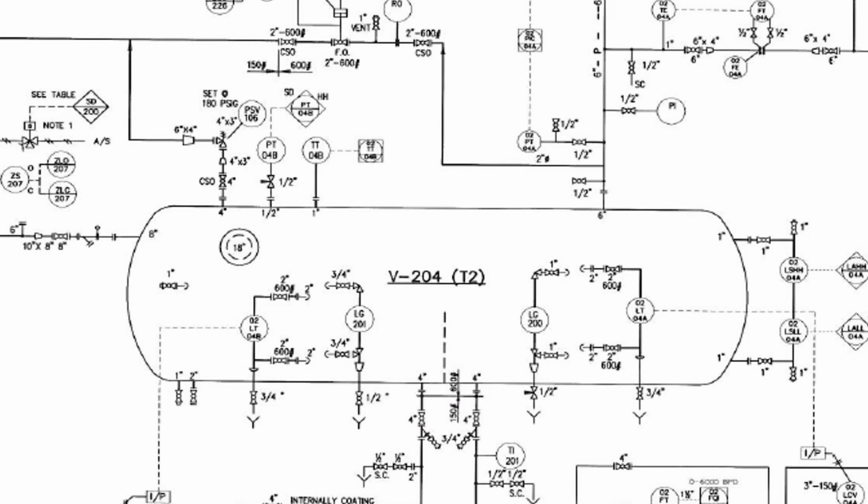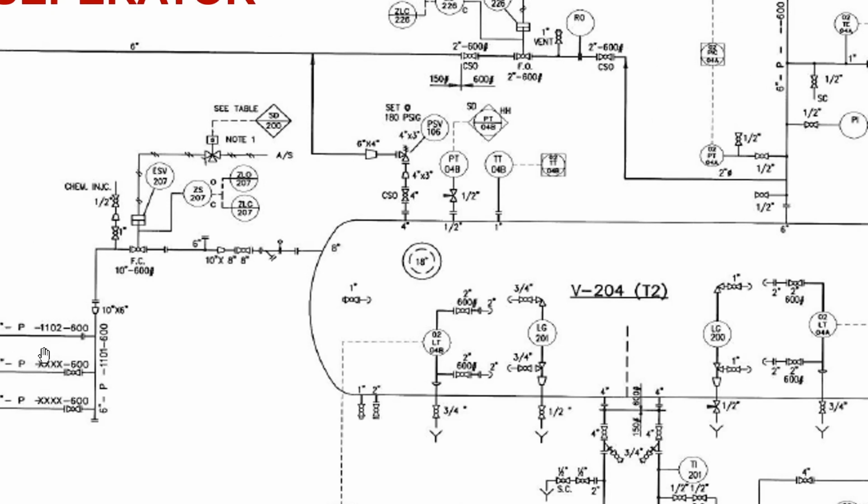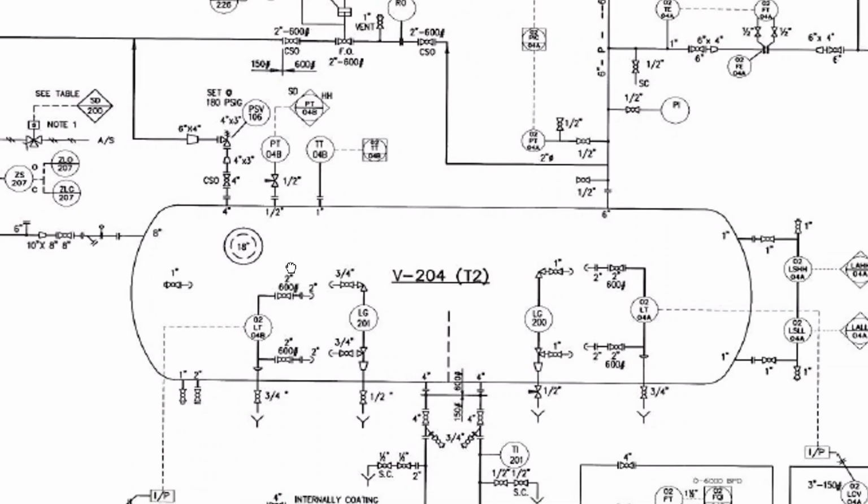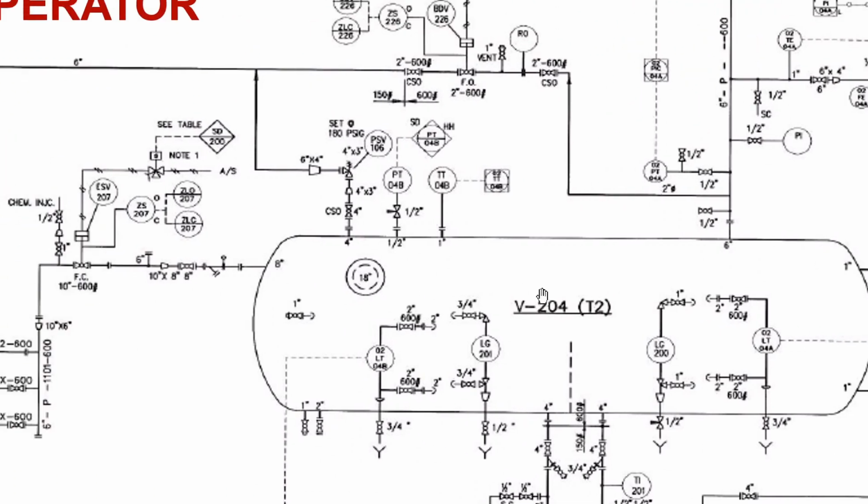Pressure and level are the most important parameters monitored in a separator. Gas outlet pressure, and most of the time inlet pressure also, they will check. It is not shown here, but maybe somewhere on the suction side there is a suction pressure to the separator, which they will definitely monitor.